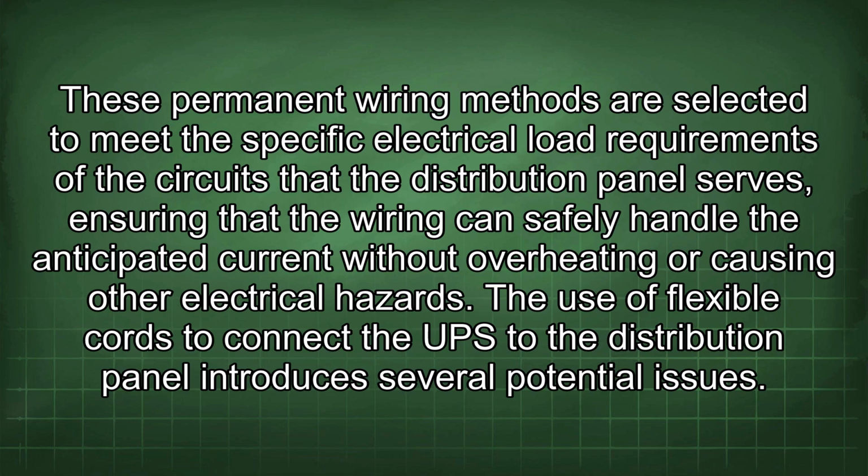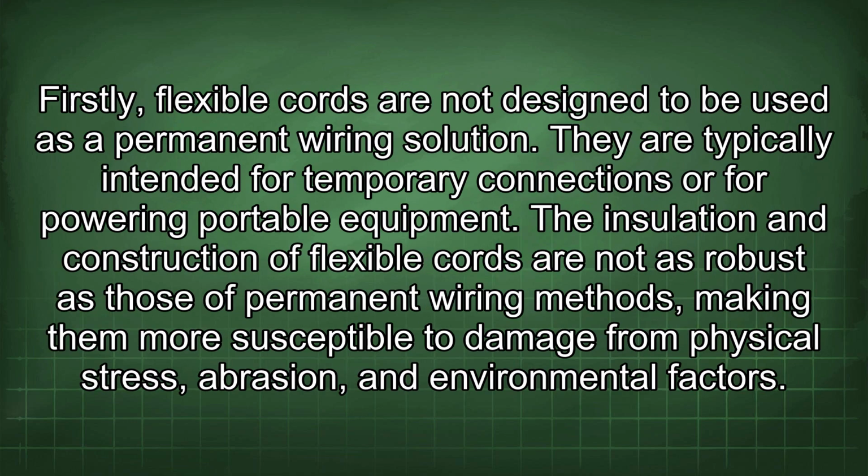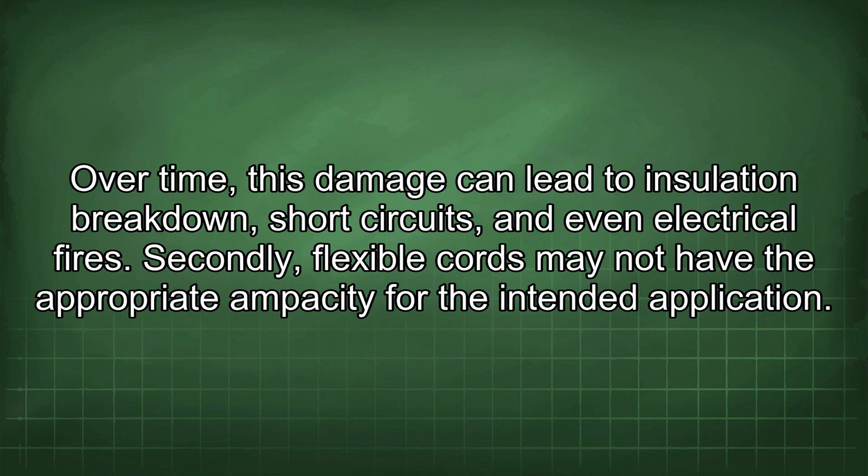The use of flexible cords to connect the UPS to the distribution panel introduces several potential issues. Firstly, flexible cords are not designed to be used as a permanent wiring solution. They are typically intended for temporary connections or for powering portable equipment. The insulation and construction of flexible cords are not as robust as those of permanent wiring methods, making them more susceptible to damage from physical stress, abrasion, and environmental factors. Over time, this damage can lead to insulation breakdown, short circuits, and even electrical fires.